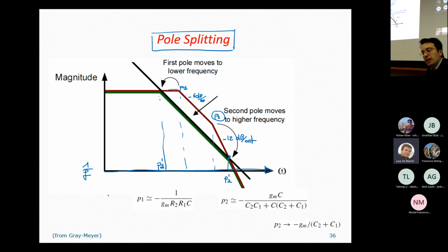Okay, but here we have high impedance, so I5 must flow through the capacitance, and the charges are then subtracted through I5 from this node here. However, when we decrease the voltage at this point, we are enlarging the VSG of this transistor.